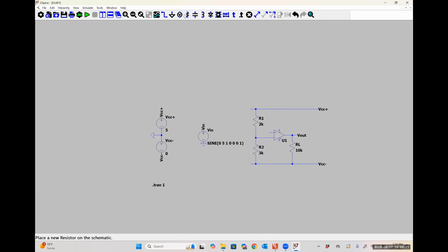And the last thing that I need to do, oh, I need to wire up my supplies. Is put in VN. Actually, sorry, that's not going to work here, because the supply terminals are on the opposite side. So I'm still just going to label those guys. For whatever reason, when they designed the op-amp schematic symbol, they put the positive supply voltage on the inverting input side. Actually, I know exactly why they did that, because the overwhelming majority of the times you're using op-amps as negative feedback circuits, and it's more convenient to put the inverting input terminal on top. But anyway.